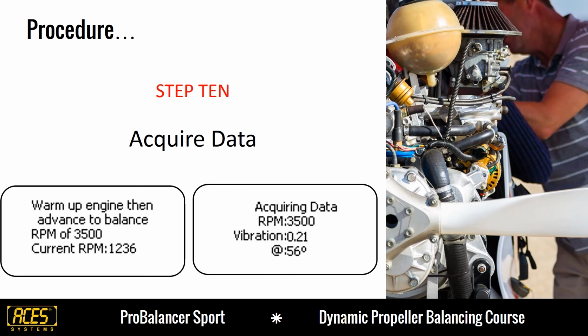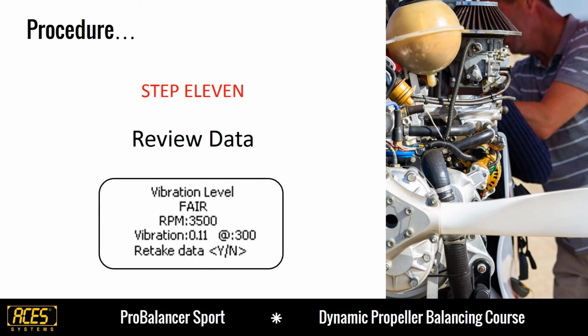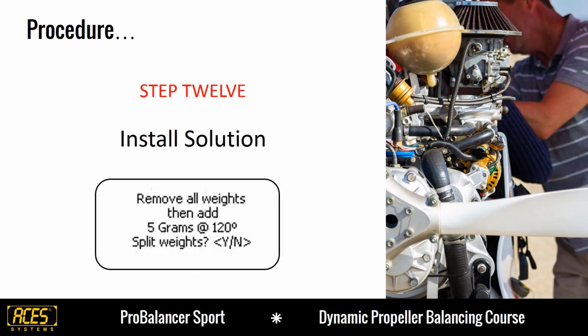After placing the test weights, you will now repeat the data acquisition by starting the engine and following the analyzer's prompts. Review the data and decide whether to retake or accept it. The ProBalancer Sport will now ask you to remove all the weights and provide you with the location and weight for the permanent solution. If you're unable to install weight at the suggested location, you can ask the analyzer to split the weights, and it will calculate 2 locations and divide the solution appropriately.